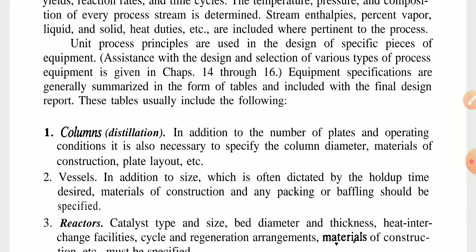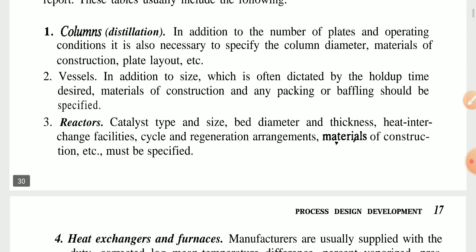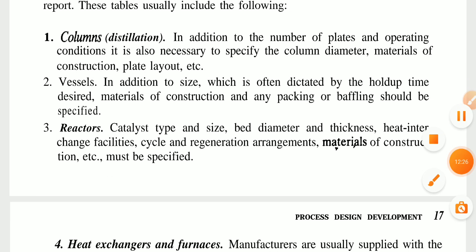included in the specific cases, and these tables usually include the following points. The first is the column, distillation column, in addition to number of plates and operating conditions. It is also necessary to specify the column diameter, material of construction, plate layout.